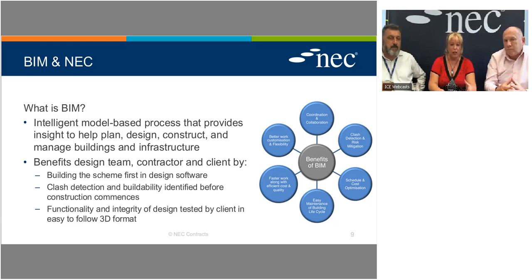It benefits the design team, contractor and client by building the scheme first in design software. On the drop-down level, clash detection, very easy things to pick up in the first instance, and how the buildability can be identified before any turf is broken, allowing the client team to test the functionality and the integrity of the design in an easy-to-follow 3D format.